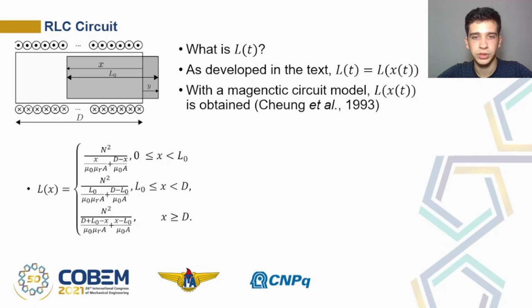Although the model described seems effortlessly simple, with only two equations, the inductance function is complex. In this work, we developed the expression for the inductance as a function of the displacement of the moving plunger. We chose to express it as such to make it easier to connect with the mechanical system. This model could result in a discontinuity from the high value of inductance that happens when the plunger is completely inside the solenoid for a rather small instant of time.